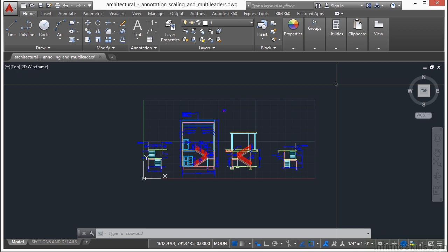So this isn't something that you're going to use all the time, but I did want to show it to you to help you clean up your drawings, because a lot of times when we first start off, we do duplicate our line work accidentally, inadvertently, just because we're not used to working with it. So if you find you're snapping to something that doesn't look like it's there, but yet it's there, try the delete duplicate function, and maybe it'll help clean things up a little bit.